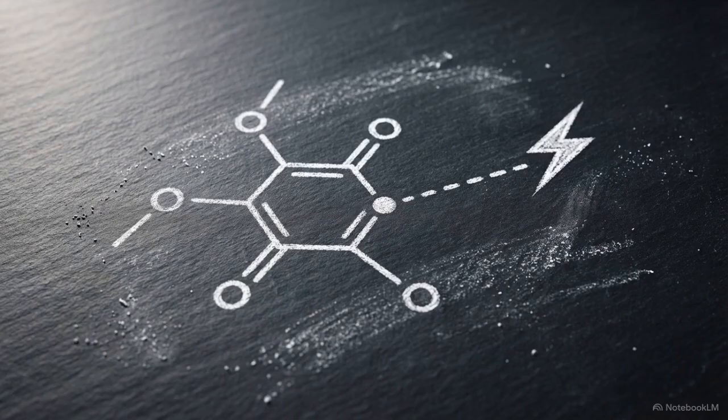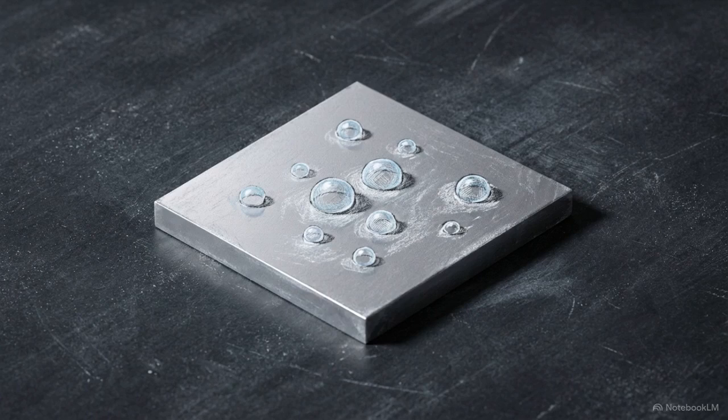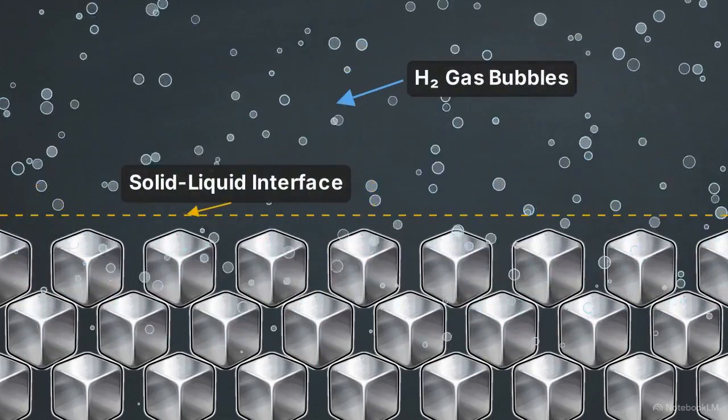Once the surface is active, we need an electron donor. In nickel-based baths, sodium hypophosphite is the most common reducing agent. Hypophosphite molecules oxidize at palladium sites, releasing electrons that reduce nickel ions into a solid layer. Simultaneously, elemental phosphorus embeds into the matrix. This inclusion disrupts the standard nickel lattice. As phosphorus increases, the grid loses its order, creating an amorphous, non-crystalline microstructure. This specific redox pathway also generates a continuous byproduct, hydrogen gas, which bubbles rapidly at the solid-liquid interface.